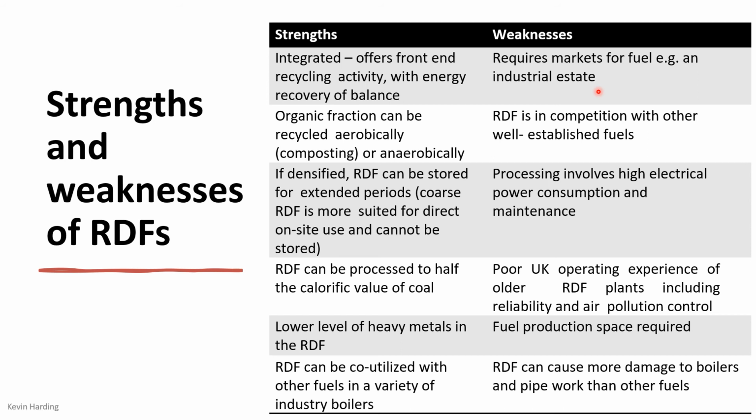It also has, and just coming down to the bottom one here, it can also cause more damage to the boilers, mainly because we don't know what is in certain of these wastes. So depending how well you separate it or classify your waste beforehand, if you're just throwing any old rubbish, literally and metaphorically, into this system, it will damage your pipework faster than other fuels when you know exactly what's in it.